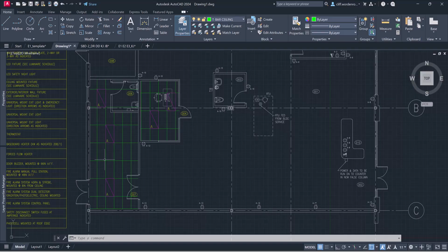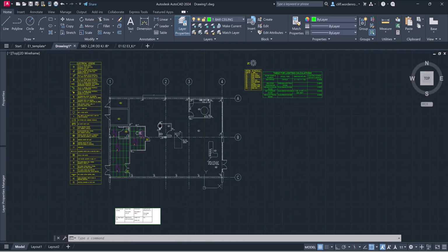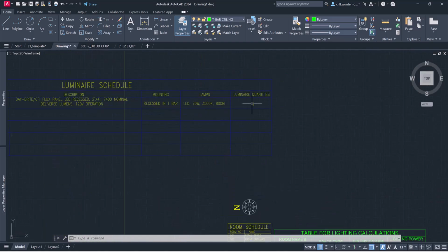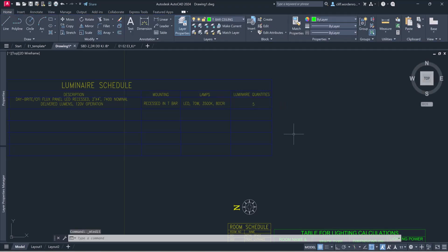Anyways, I think that's okay. Again, you could put it here if you really wanted to. Yeah, I think 3 is definitely a minimum. I would almost bank on 4 as a higher number to get in there, but it is a long, narrow room, so it's not too bad. So anyways, once you've analyzed that a bit, maybe get your instructor to review what you want in terms of lamps in there. We added 3 more of these exact same ones. So what we can do is come up here and update our quantities now to 5. So that's the total amount of lamps that are in here.